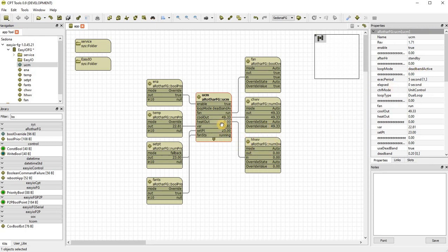So even though it's not quite at set point, as part of your configuration in setting the loop up, you've decided that if it's within 0.2 degrees of set point, we don't really need to start micro adjusting the chill water valve to run it directly at 23 degrees, because really, who can tell? It's so close to set point, it seems ridiculous to start micro adjusting valves to try and maintain an exact set point. There are circumstances where you need to do this, but generally speaking, not. So that gives us our deadband option.